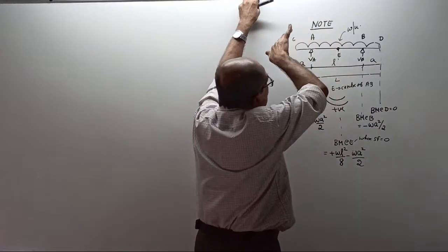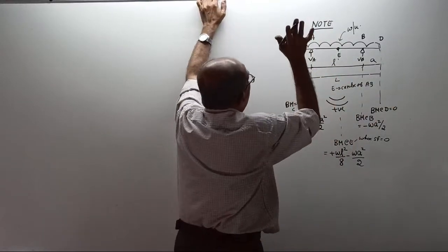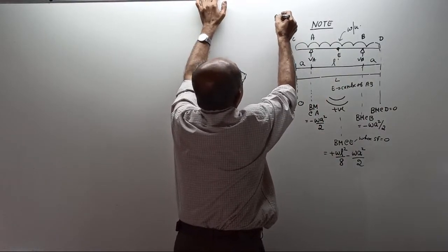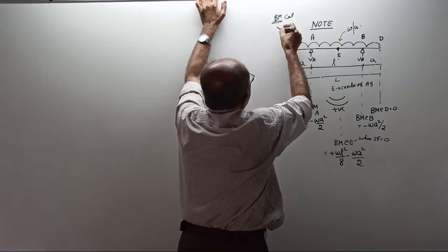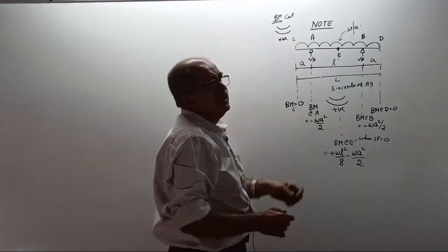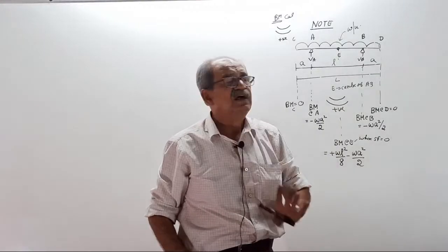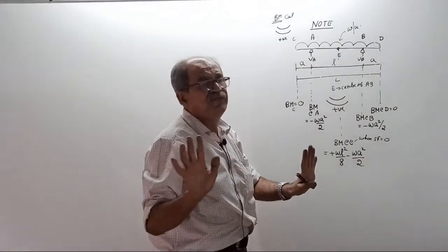Now come to the inner points. Our discussion, the bending moment calculations and expressions, are based on sagging positive. Very, very important, since small points sometimes give confusion and a wrong version. So all I have written here is based on sagging positive.